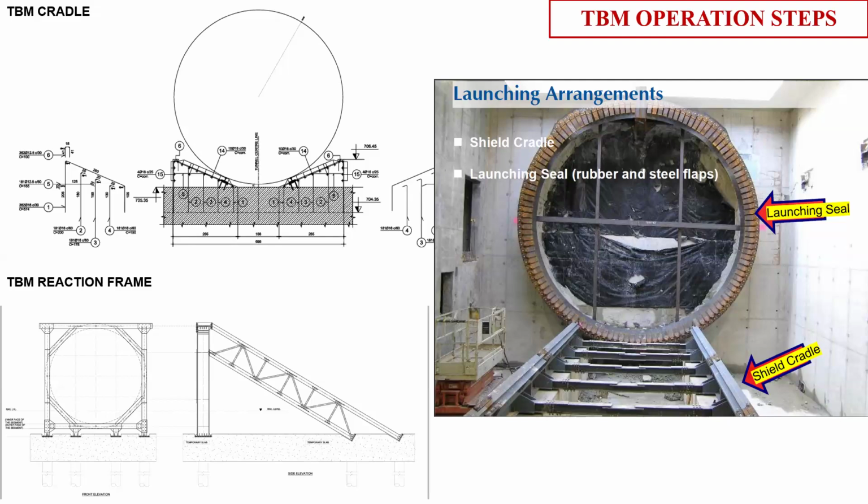It can be a diaphragm wall, a secant pile wall, a contiguous bored pile wall, any type. Whatever the gap or interface there is during the breaking, if water ingress is there, to control the water or stop the ground from collapsing, we put a sealing ring.